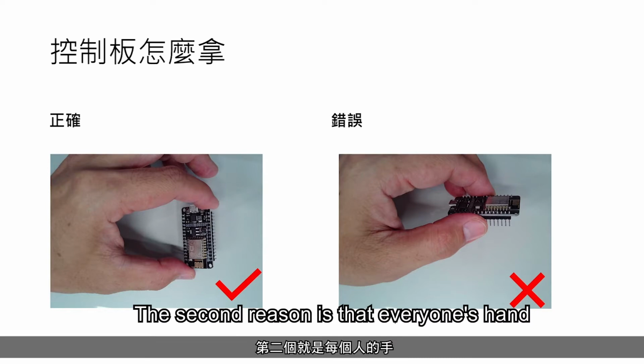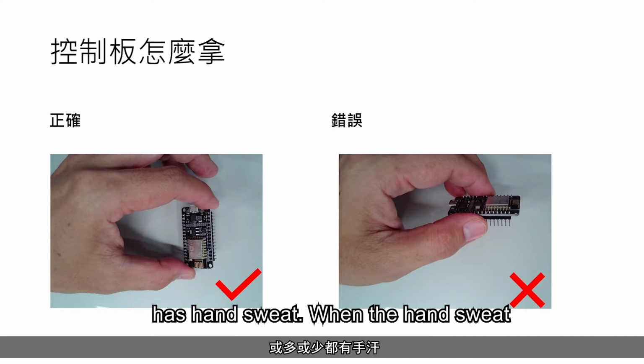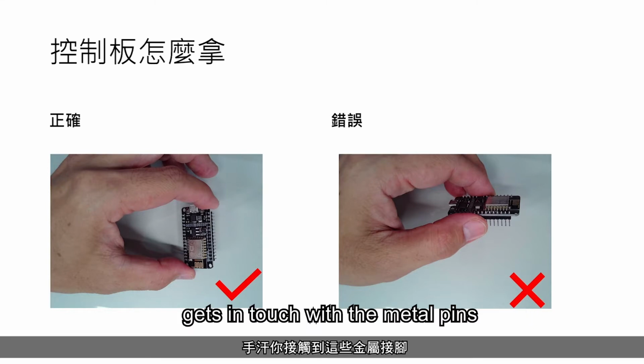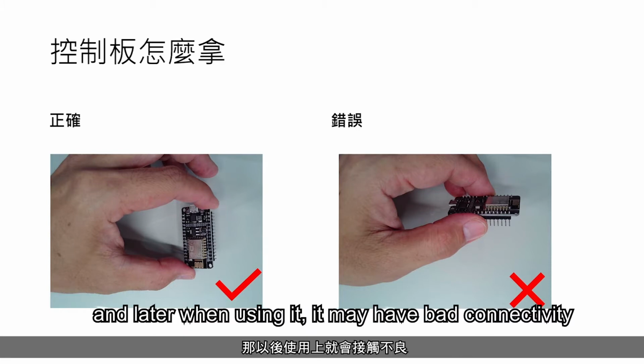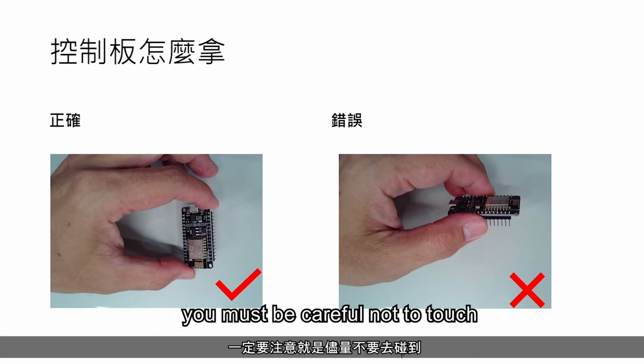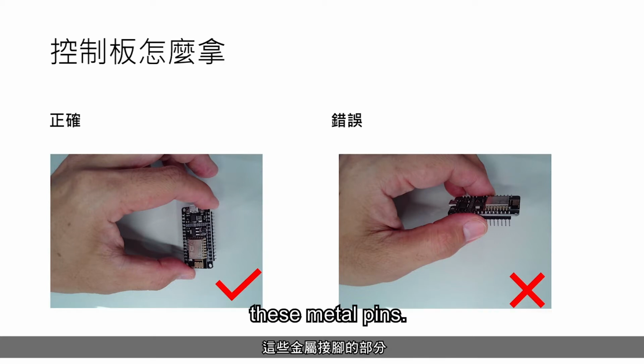The second reason is that everyone's hand has hand sweat. When the hand sweat gets in touch with metal pins, it may cause oxidation, and later when using it, it may have bad connectivity. So when grabbing the control board, you must be careful not to touch these metal pins.